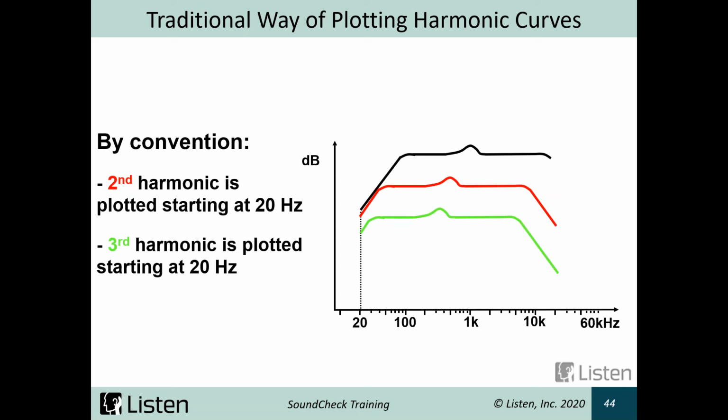This was done for a couple of reasons. So, in the past, analog test equipment was synchronized to the signal generator. So as you were playing 20 hertz, you were drawing your fundamental, you were drawing your second harmonic, you were drawing your third harmonic, etc. And it's also a little easier to read distortion in a percent by comparing the harmonic to the excitation frequency. So all THD that's on published materials, most spec sheets are going to have distortion using this method.